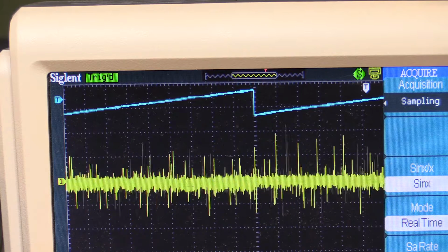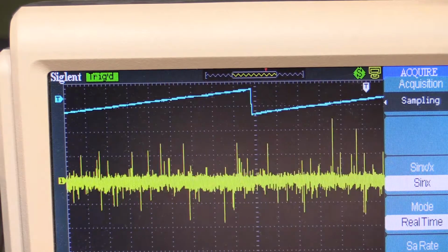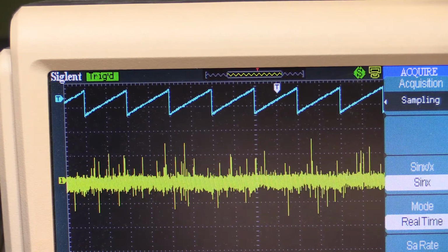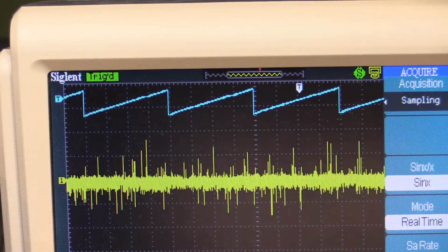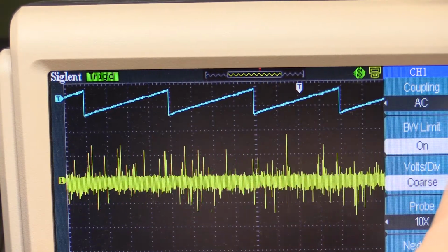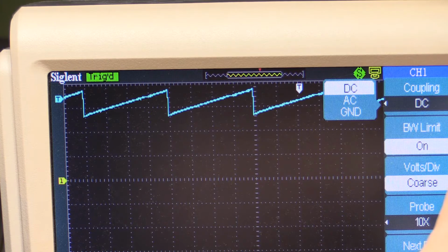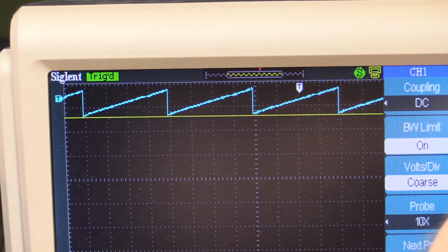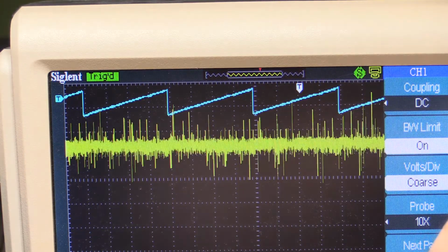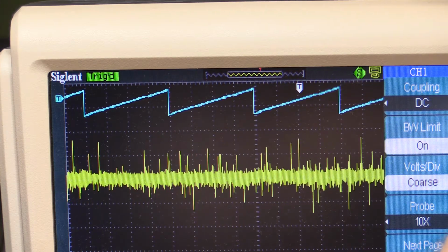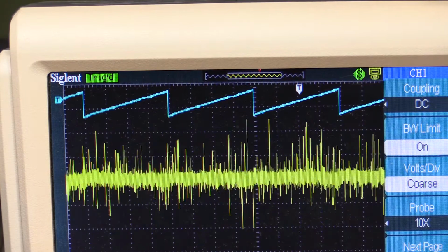all right, there's no detectable changes here. If I just reduce the frequency, reduce the time base slightly, and change input 1 to be DC coupled, of course, it's off the top of the screen, so I'd have to drop this down to something. The output is about minus 1.05. Oh, I can get it in there. There we go. So you've got 20 millivolts per division. Now it's DC coupled, so that's pretty good.